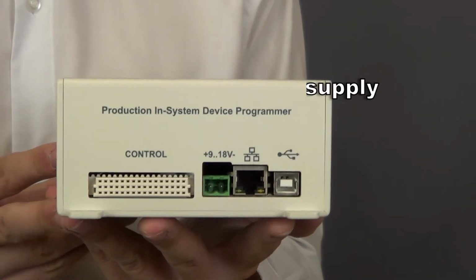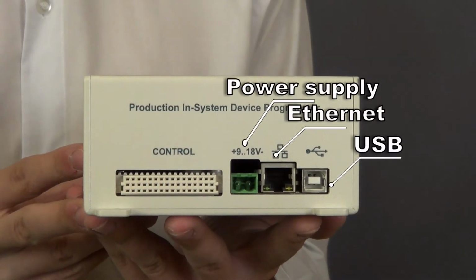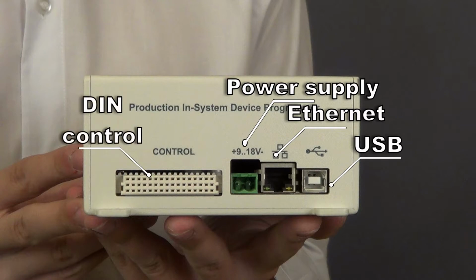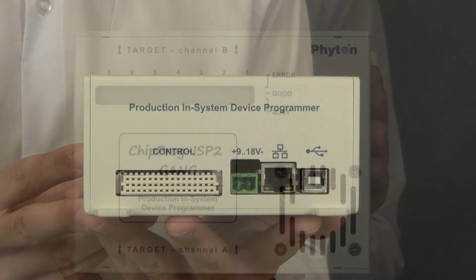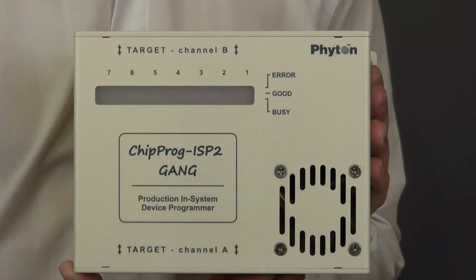The power plug, USB, and Ethernet connectors are located on the face side of the programmer. Here we also see a 48-pin DIN control connector for connecting the ATE signals. That includes the signals for tasks such as launching the programming sites, selecting standalone jobs, and outputting the busy, good, and error status signals. Each site has its own control signals that enable it to control them independently. For example, launching all programming sites synchronously or asynchronously.